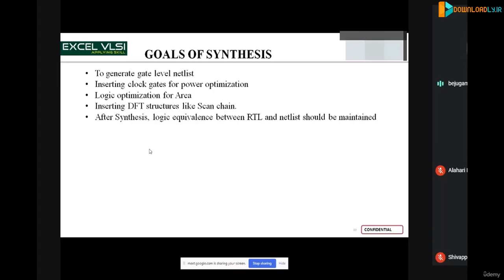According to the application point of view, the front end engineer will be defining a logic where you can introduce the scanning cells which are ready for manufacturability or productivity at this stage itself. When you are introducing those scan cells to check the controllability and observability of the circuit, you can use that scan mode, that is nothing but DFT mode, and you can introduce that scan logic at this stage itself. So when you are implementing the logic in scan mode, you need to introduce this DFT logic.